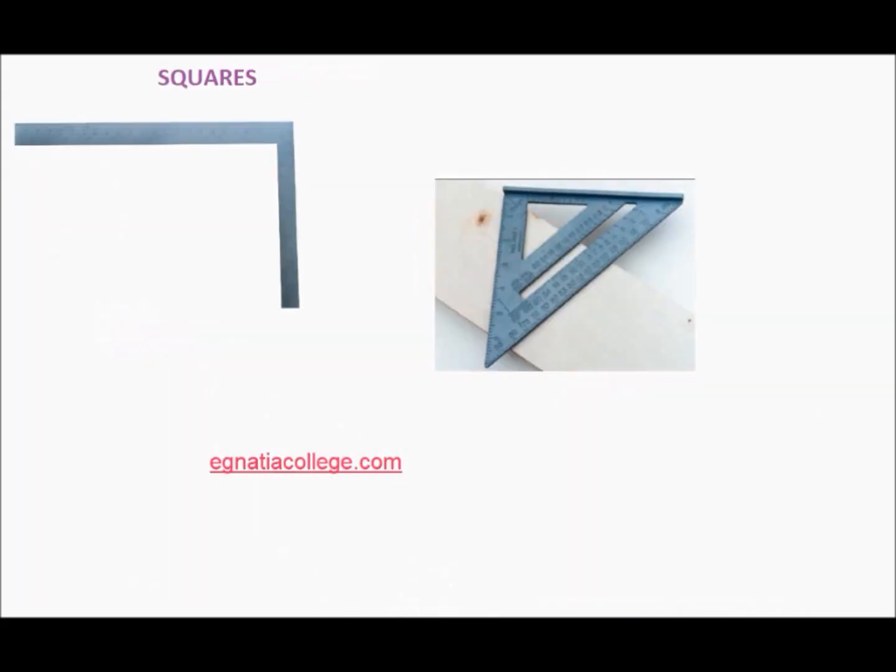Squares. Framing squares are used extensively by carpenters, whereas they are typically used by plumbers for layout or when marking large boards to cut. Both types of squares have dimensions included to use for measuring and layout. As you will learn in the material section of this book, plumbers use 3 basic offset angles. 90 degrees and 45 degrees angles are the most common angles, and 22 1/2 degrees is the less common, used for drainage and vent systems.